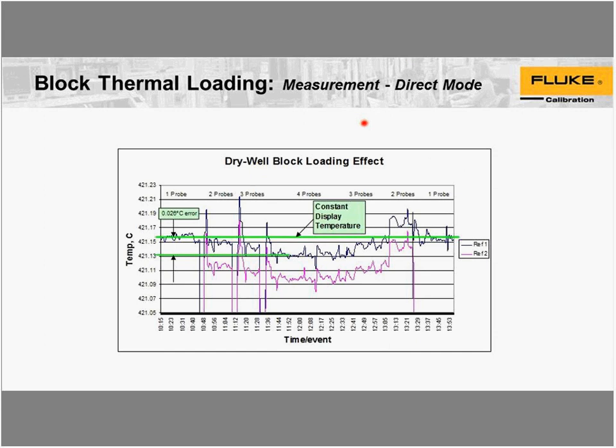In a minute, this is a measurement now of how you can test that. And you can do that with the types of probes that you use. I've got a dry well going along here at 421 or so degrees C. Our first probe we put in there is a value, and we're going to say that value is whatever the set point is. And then, of course, this point is going to stay the same, so the display is going to continue to read that same value during the entire process.